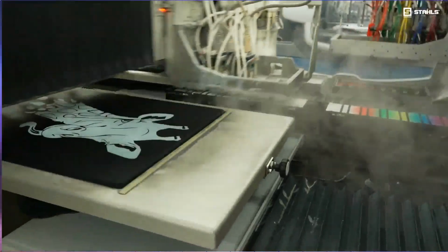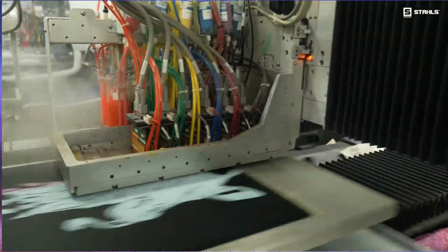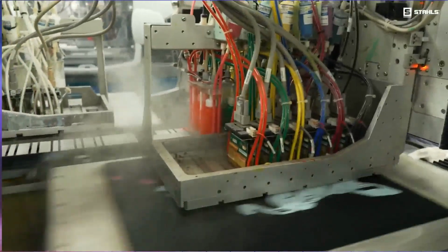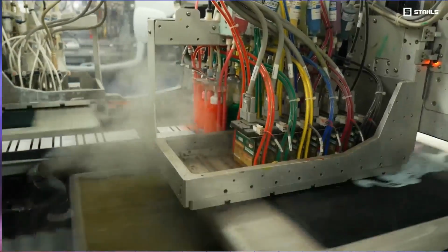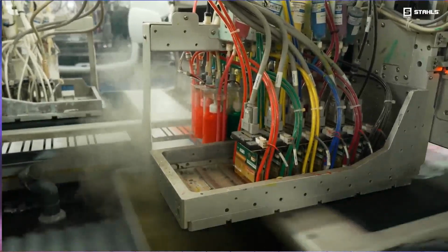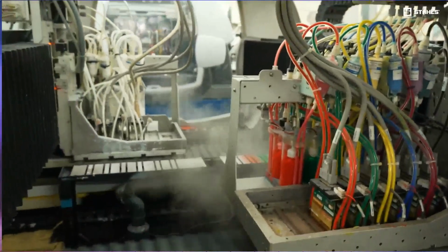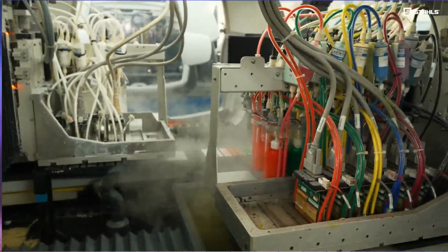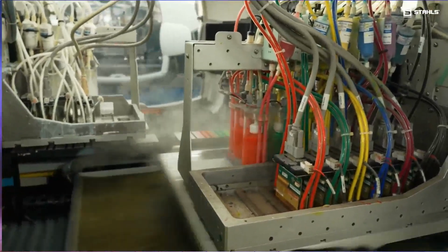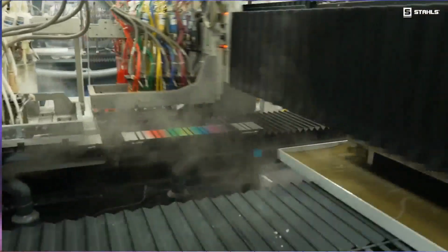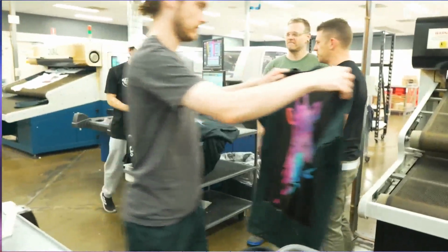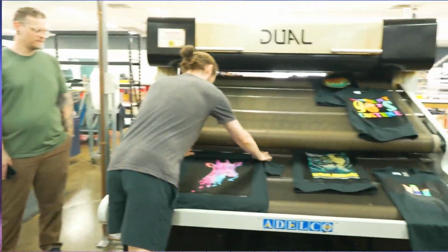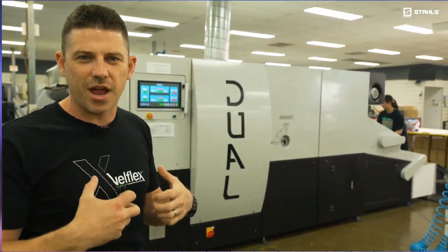The next process is obviously printing down. Now, when we're printing onto t-shirts here, going onto dark colors, onto colored garments, they've got to print down a white base first. So you have a thick white layer going down, and then you have the color on top. Okay, once that printing is done, we've then got to cure the shirt itself. So we see these bigger dryers off to our side, guys, and you can see the size of them here. These garments are all going through that curing process where they're fixating that ink onto the actual garment itself.